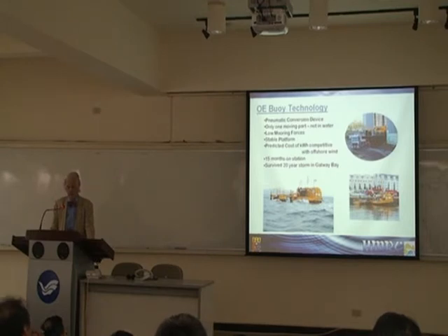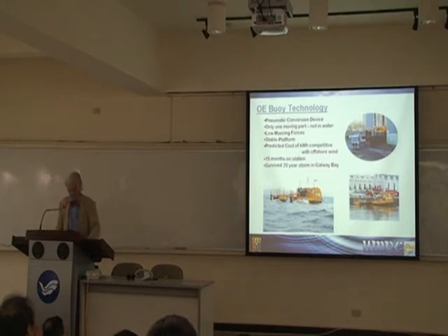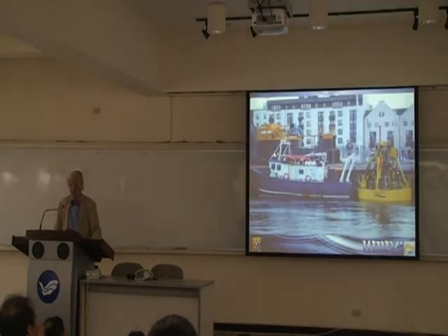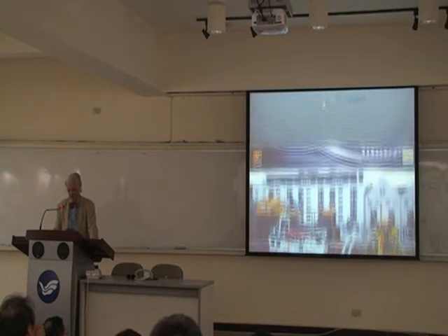So they also have been working in the wave tanks with phase 1, 2 and 3, and they then have moved into the Galway Bay test site with their quarter scale model, which is 12 meters long, weighs about 30 tons, and here you can see the device being brought out of the construction yard on the transport, then lowered into the water and brought out onto the site, where most of the device is under the water. You can see the air turbine at the top here, where the air flows in and out to generate the electricity.